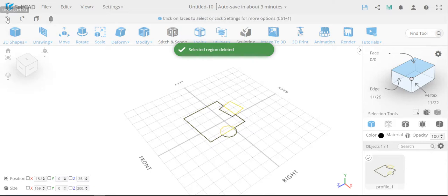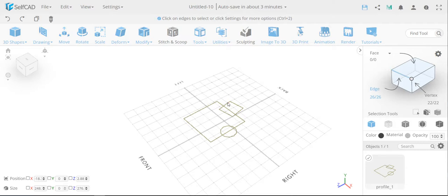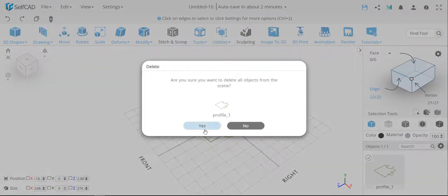Or you can do the edge selection mode, and in that case, it will select just edges instead of polygons. So you can select, let's say, just this part and just this part, not really polygons, and start cutting. You see, just pieces from the circular shape and so on, and start deleting them. So that's basically one way of cutting profiles. That's kind of trimming, basically.